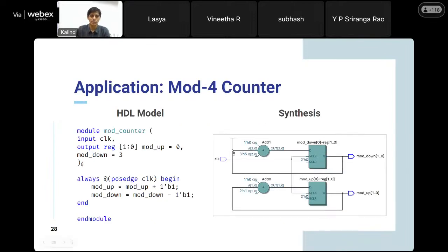The Verilog code that you write in the CAD tool, Quartus for example, after you synthesize it and get the netlist, a compilation report is generated. That report will tell you how many logic elements your design is taking, how many registers it is taking, and how many memory bits it is consuming. Based on that report, you can figure out the right choice for selecting an FPGA.